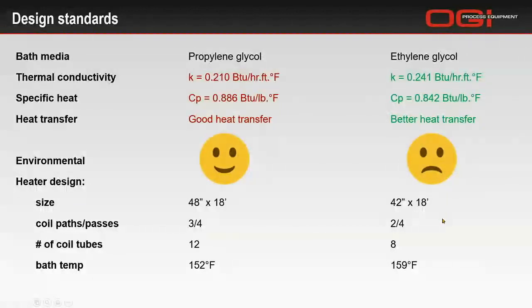May not seem like much, but imagine how hot your fire tube, which is the engine of the operation, has got to get in order to warm up your bath to that level. And you're going to get into situations where you're going to start scorching and burning your glycol. Propylene glycol is even more sensitive to heat. The limitation for propylene bath, we would say between 170 and 175 at your maximum. So now you're working with 184 degrees and you're really starting to degrade your propylene glycol.